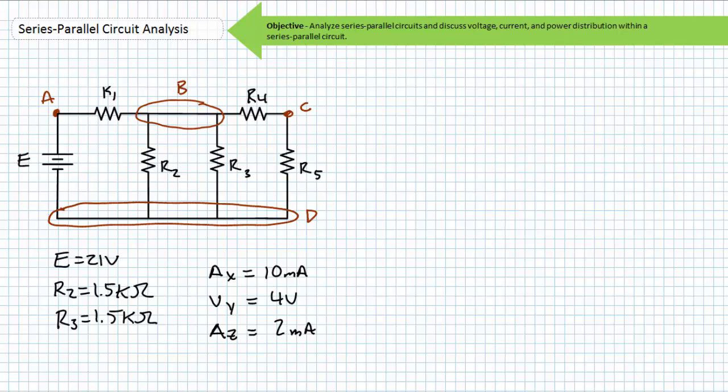The first step in series parallel circuit analysis is to visualize circuits at the nodal level and from the perspective of flowing current. Current in a single path is the same. Voltage across paths in parallel is the same. For every rise there is a drop, and what goes in must come out. Remember to review these concepts as often as you need to really drive it home. Imagine how well lab will go if you know what you're doing.